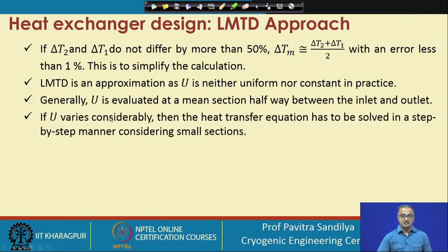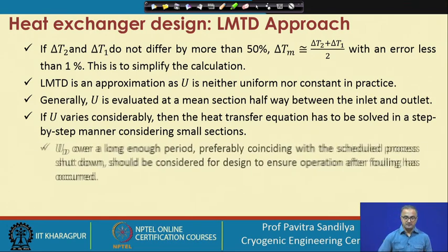And generally this heat transfer coefficient is evaluated at some section halfway between the inlet and the outlet, and if the U varies considerably, then we cannot use this LMTD. We have to go step by step, taking the actual temperature difference between the two fluids.